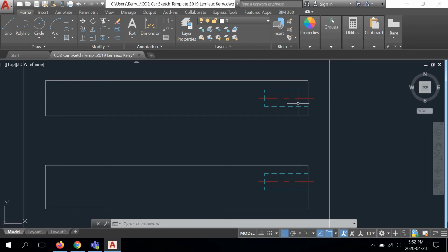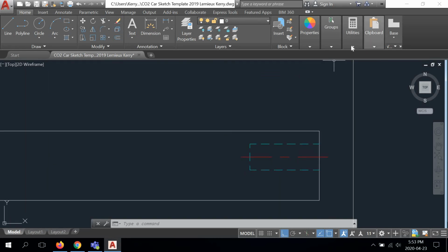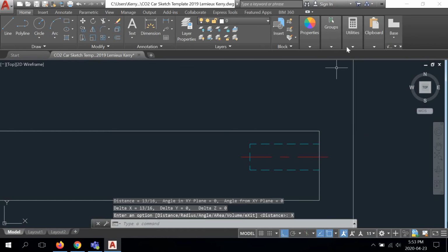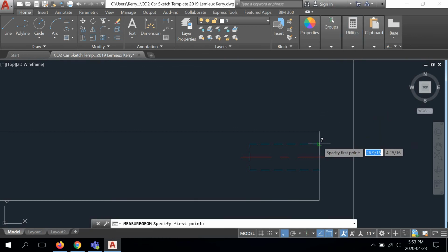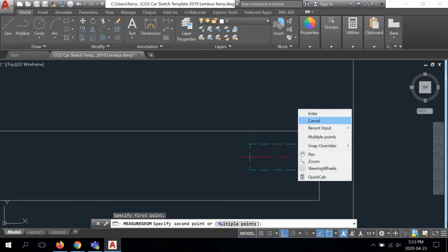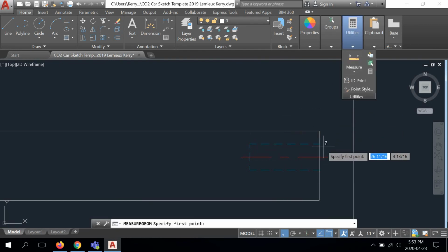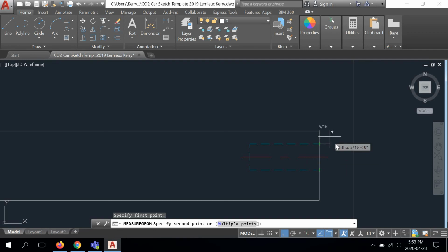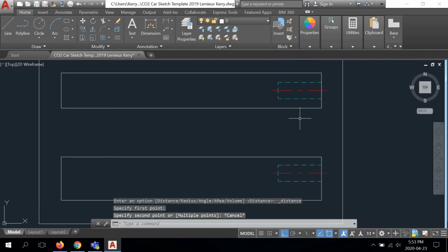If you're doing this drawing by hand on paper, unfortunately you have to find the middle, which is easy to do on the grid, but again, AutoCAD has its certain advantages, as you can see. So let's check some things, right? Let's measure. Let's go to the measure tool. So this should be 1 1/4. Yes, it is. And the length should be 2 inches. Yes, it is. And the diameter of it should be 3/4. And yes, it is. So everything is being done correctly.